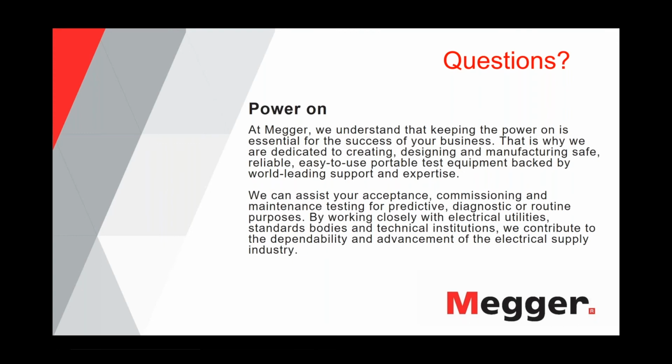Now, the tricky part is you will get, as Javier explained, this kind of traffic light system, okay? You will get no action required, further study advised, and action required. Now, as Javier also pointed out, action required does not necessarily mean the cable is completely bad and will fail the next day.